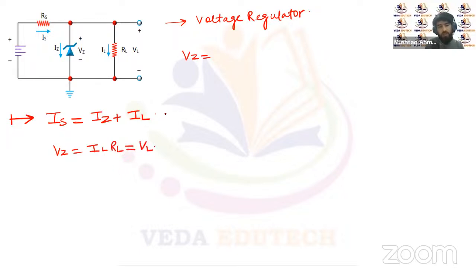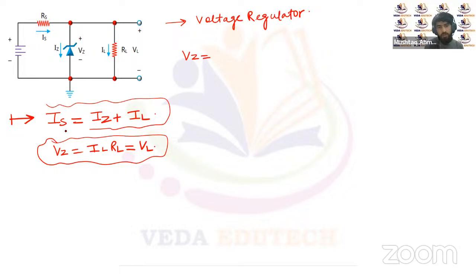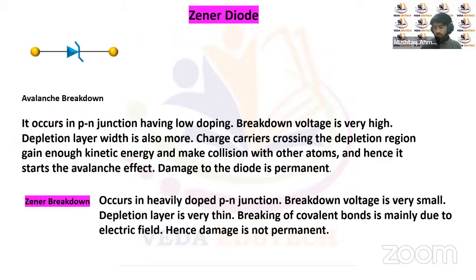So this is how the Zener works in the breakdown region or reverse bias condition, and it helps in regulating the voltage across any load connected directly to the Zener diode. So it's one of the important applications of the p-n junction diode. That's the Zener diode, and it's used to regulate the voltage across any electrical element or circuit because of the nature of the Zener diode that it only works in the breakdown region. That's what we call the reverse breakdown voltage.